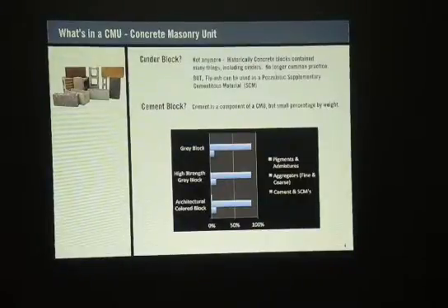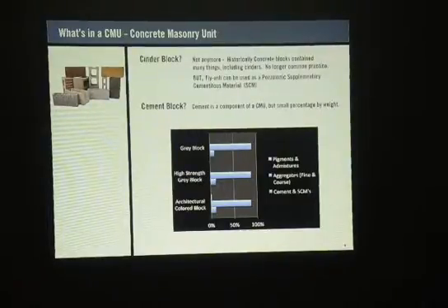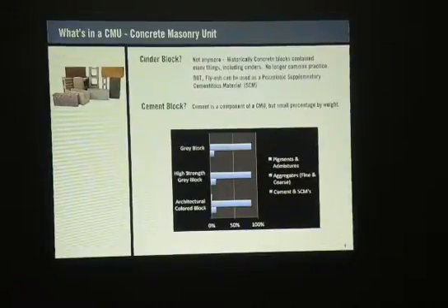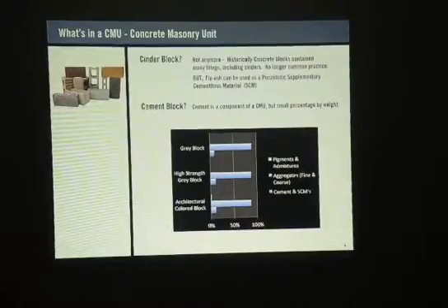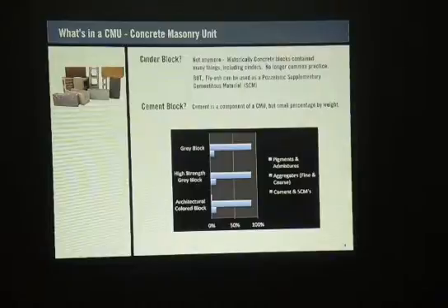Great question. Thank you. It's the block itself, and we'll have something on ASTM later, but to answer your question, the block itself, when ASTM became the governing body of CMU and concrete block, started out at about 1900 PSI compressive strength or greater, okay? But in 2013, in a nationwide wholesale change, it went up to 2000 PSI compressive strength.